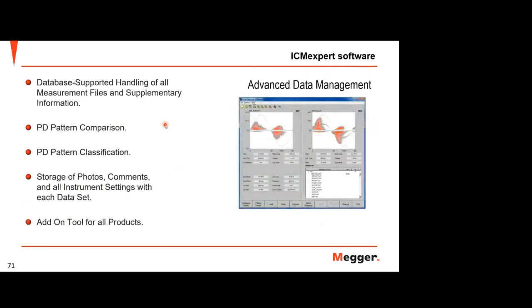And also, one software can be used to help you analyze what type of PD it is. We have the ICM Expert software. After you get the measurement, you just upload and analyze, and the software will try to find from our database a PD similar to what you got. Finally, you can see the final PRPD type recommendation by the software, with some information, a percentage of similarity.